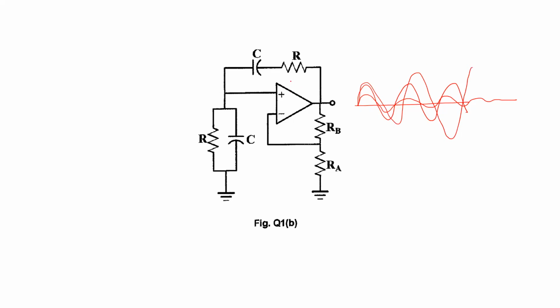And then if the op-amp is powered, let's say by plus or minus 5 volts, then at some point, the highest the output could get is plus or minus VSAT, which let's assume is close to the power supply. So at that point, it's going to get close to here and try to get bigger. So what's going to happen is that the output is going to do that, clip, do that, clip. And then eventually, if it keeps getting bigger and bigger, all you're going to get at your output is going to be looking something like that, right? In other words, the output saturates.